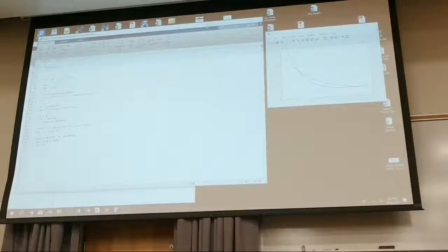It's because of the values between the sample spacing. We went from 0 to 16 as our range, but we only got 2 to the 4th, or 16 values, right? So they're separated by 1 second. Think about it. First value is at e to the minus a0, or e to the 0, which is 1, right? Next value is e to the minus 1. That's a huge change. That's only 37% of the original sample, right? The first is at 1, the next is 0.37. So you don't expect a good comparison. At least you can see trends.